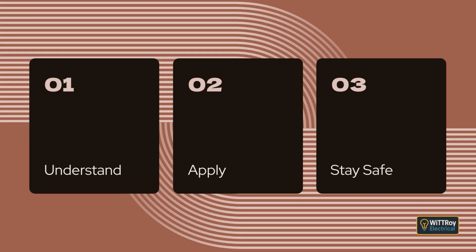Clause 2.3.2.1.1 Alternating current systems. In AC systems, all active conductors must be isolatable. A neutral may only be switched in special situations, and when it is switched, it must open and close together with the active conductors. The neutral must never be left floating, as this can create dangerous voltage levels. Some circuits, such as fire pump controls, have special rules, but the general idea is simple: actives must be able to be isolated, and neutral switching must be safe and properly linked.